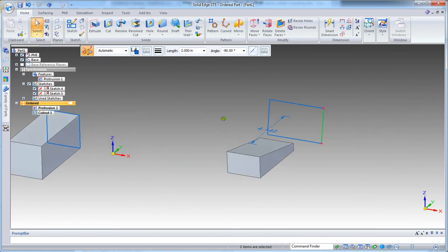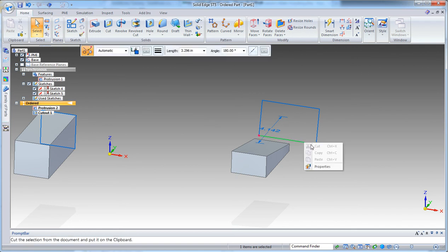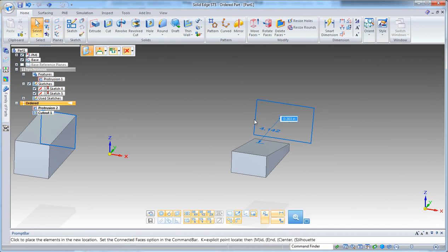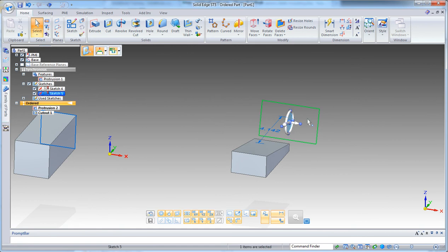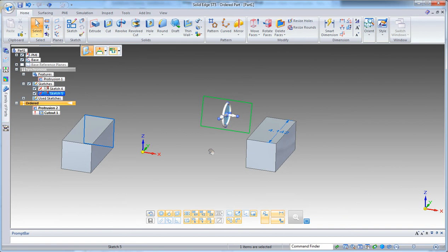And then some of you will say, yeah, it's a synchronous part, and then you have consumed a face, so you cannot retrieve that face. Well, sorry. If I'm waiting and I pick my sketch and I move it here, you see that even if it's a synchronous extrusion and I consume a face, I can recover one of the faces. Whoops, sorry. Instead of escape, we'll place it here.